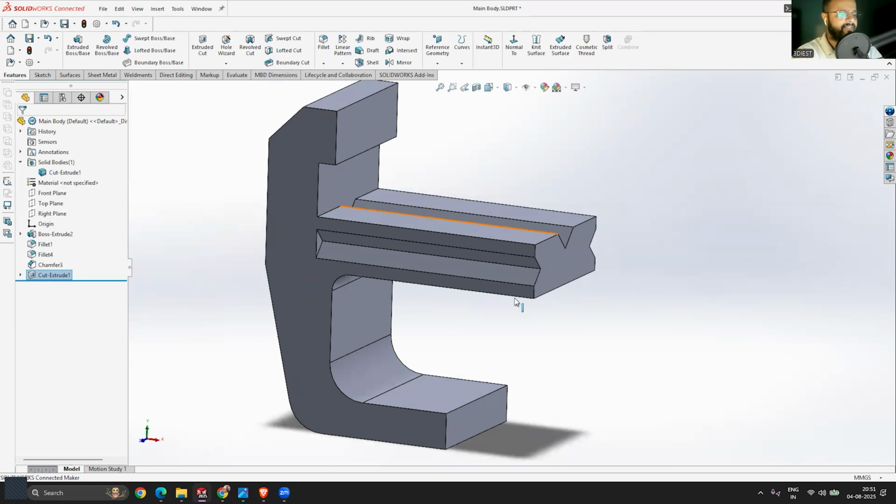Great, everyone. So now we'll start applying the rest of the chamfers. So simply we'll activate the chamfer tool, and this I will do quickly because I know that all of you know how to use the chamfer tool. Not 10 chamfer, simply 2 chamfer. So we'll add a few more edges like this edge.